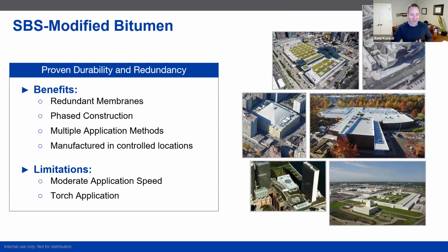Mod bit sheets are thick pre-manufactured waterproofing plies. They're applied independently in a multi-layered format. It creates a redundant configuration. It's pretty conservative. Gives you double protection at least.